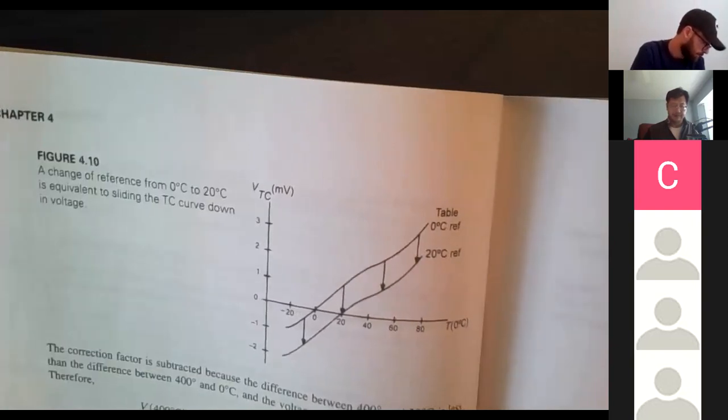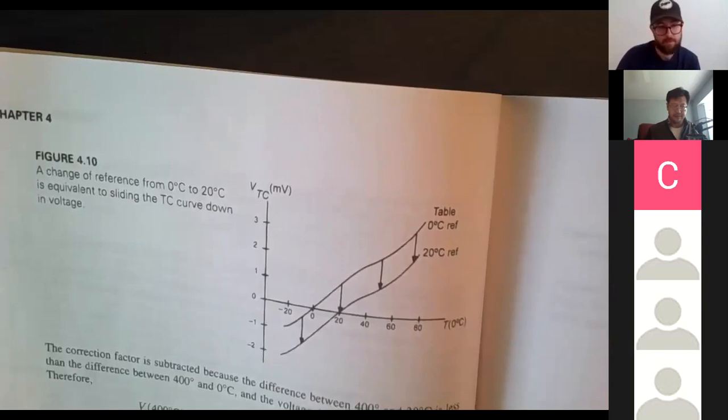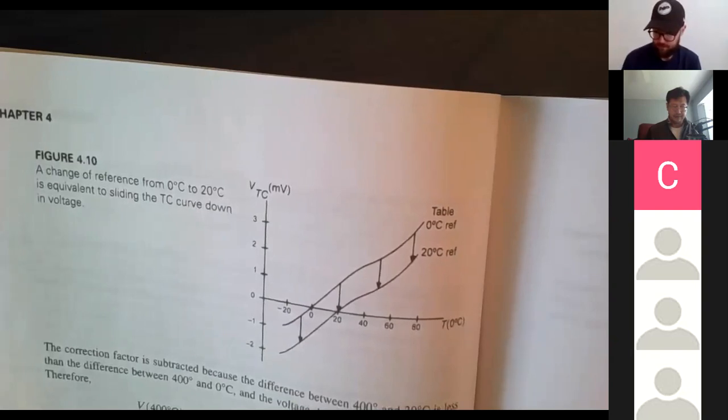And then that sensor receives a number, and it always is sensor number 1, and it always plugs into the same point in the data logger where its digital correction is. So we have to be really careful that they're tracked and they go in the same spot every time. You don't want to mix those up because then your digital correction will be off.